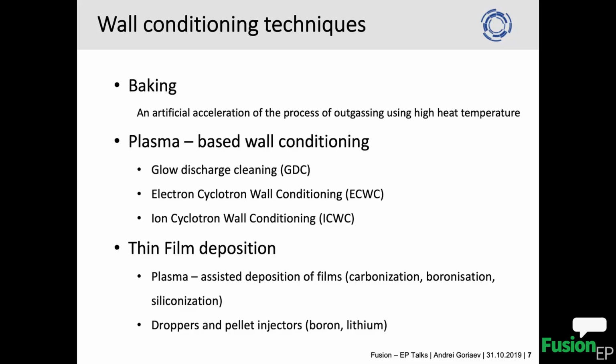So first of all, you pump your vacuum vessel and go down to a certain pressure, and then either you have to wait or you have to do something with your device to remove all these impurities which are stuck on or inside of your plasma facing components. So the first is baking.